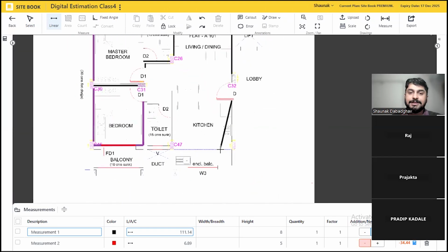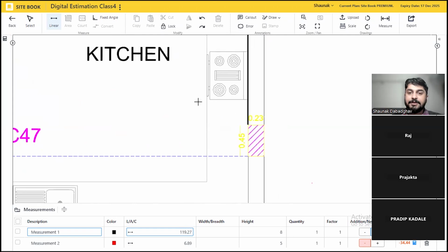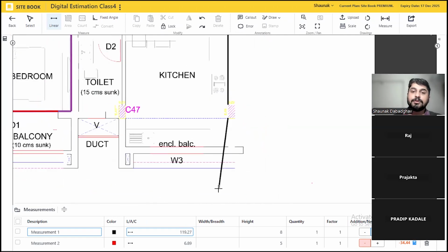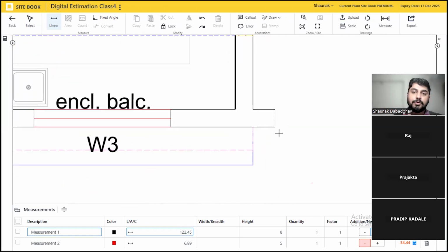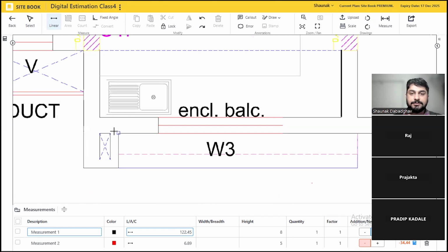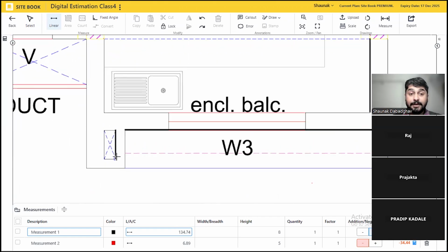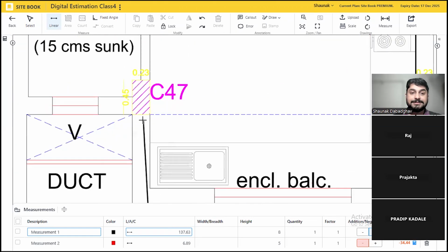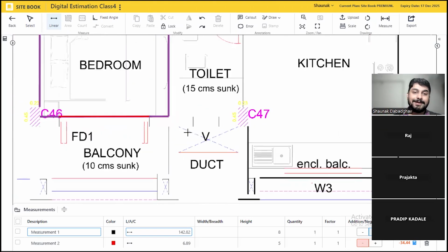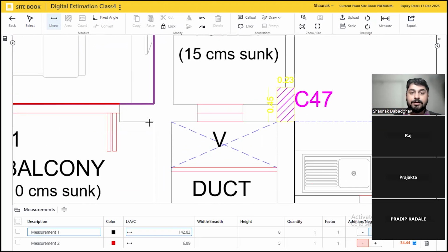I'm not considering the door as a deduction here because what developers or anybody is doing these days is taking the lintel at such a height that there's no requirement of a lintel. Your beam above the door acts like that, and your door will be till that height. Again, I'm assuming that this total block work is the same thickness. It is not, but again, it won't matter much.